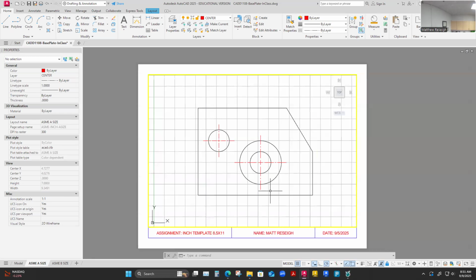I just take one last look at my lines and I say, is it showing how I want it to show on a PDF? Are my center lines broken up to where they show as center line types? Are my hidden lines showing right? I just take one last look and then I adjust their line type scales if needed. So I tend not to make that adjustment until after I'm happy with how things fit on my drawing, because a lot of the times to make things fit on the drawing, we have to do something beyond 1-to-1 and make it actually fit on the paper. And then I take another look at the line and then I apply that line type scale.